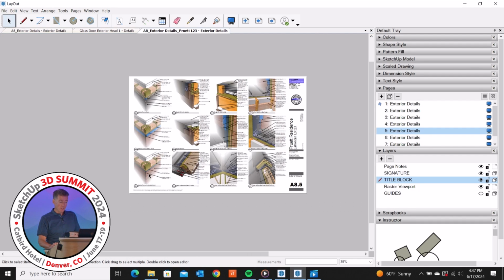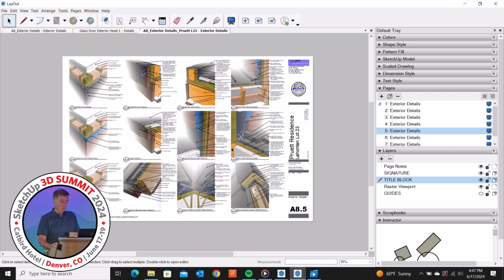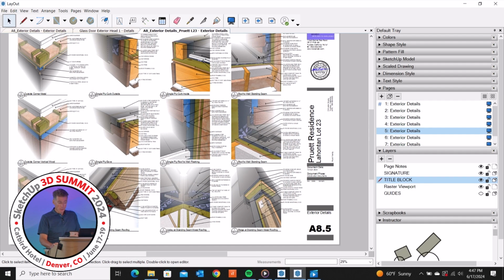And then these details will continue, especially the roofing, where we capture all the roof to wall conditions. Here it's where it's parallel, here where it's perpendicular to the roof. This roof also has a ridge, shows how we frame up the ridge cap. And you can see that's also where it's noted about the closed cell foam tight to the deck. Then we have, in this house, a valley in a couple locations, not many, I think mainly just around the chimney. And then these are all the PVC details where we have a raised curb so you don't always see that sloped edge.